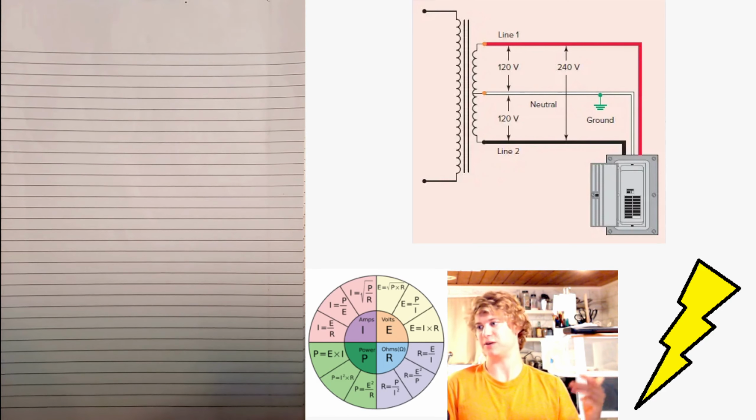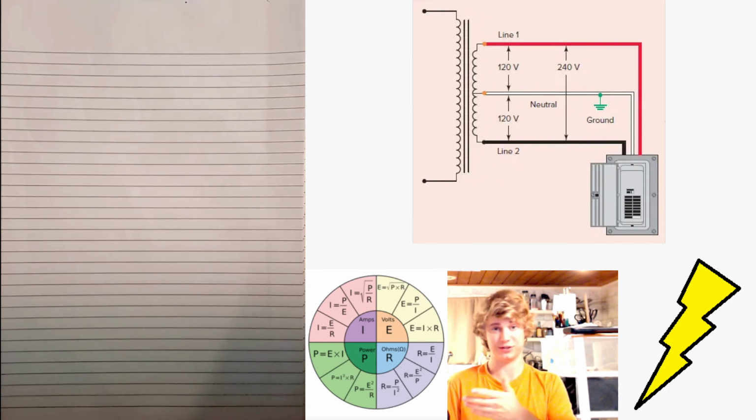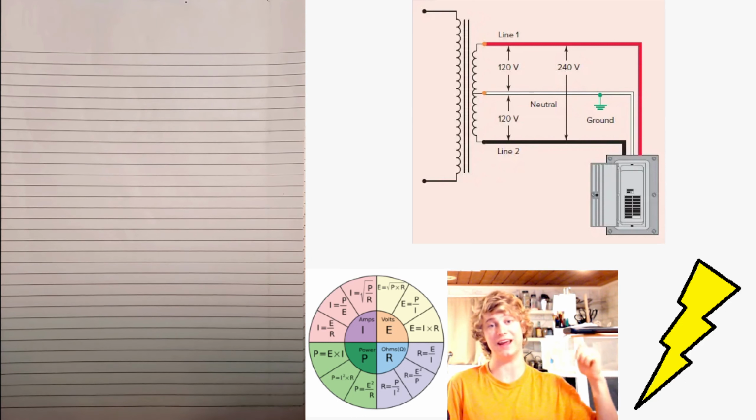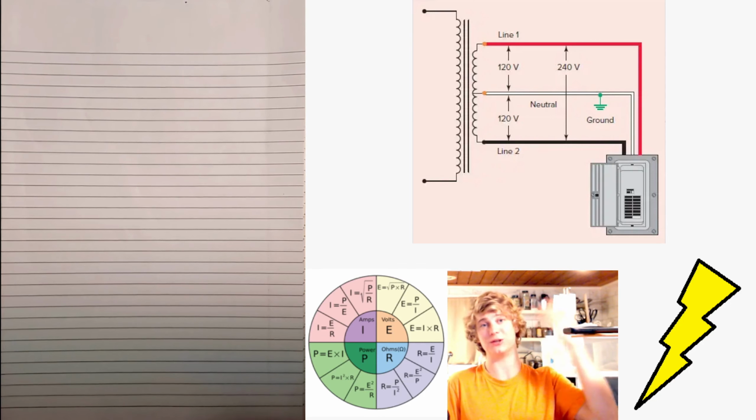The center tap allows two different voltages, 120 and 240, like I just talked about. This is from that single-phase supply. This type of voltage supply is normally adequate for most lighting and power appliances in a home. It is also known as a single-phase 3-wire supply system and also split-phase system. Its main advantage is that it saves conductor material over a single-ended, single-phase system. Single-ended meaning that you'd have one line and a neutral. As shown above, we have two lines and a neutral.